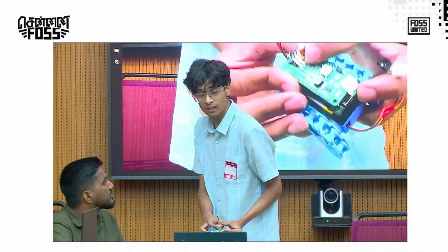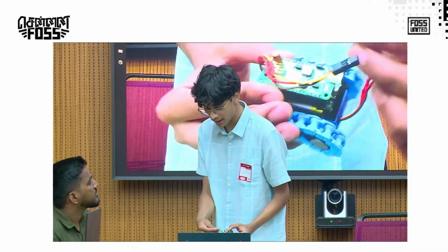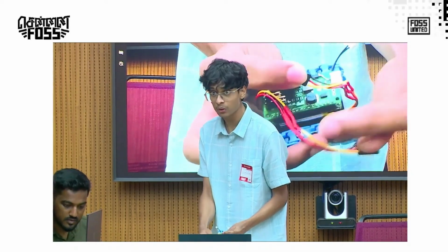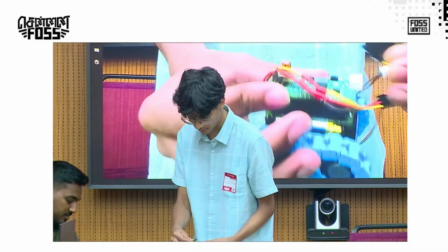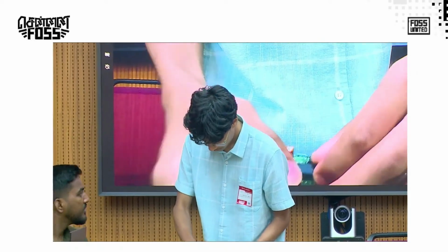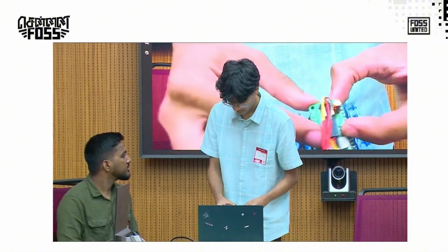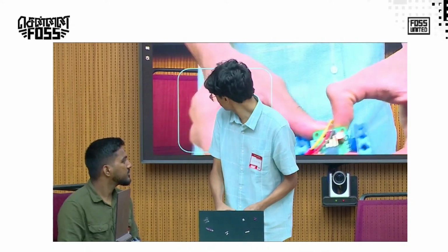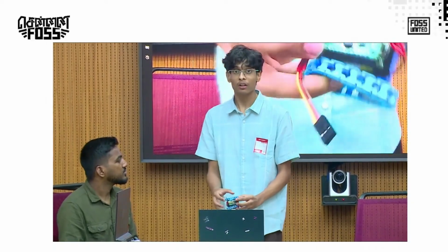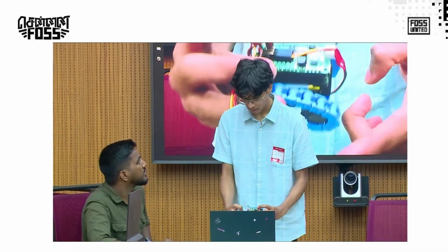You take the smaller one and make sure that the yellow wire is facing outward, like this, and you connect it like this. Make a note, everyone, because if you do this step wrong, you might actually burn the servos. Make sure the yellow wire is facing outward.